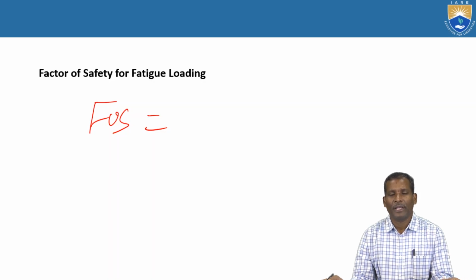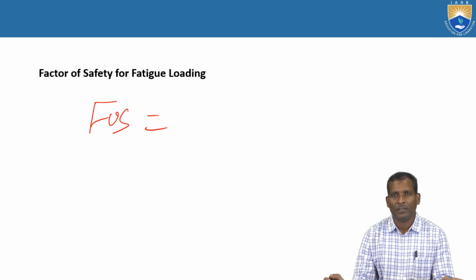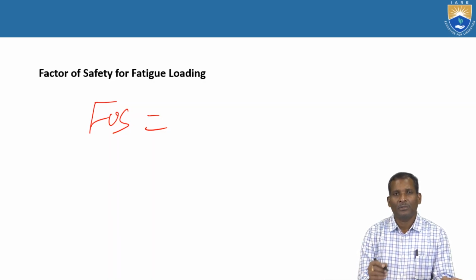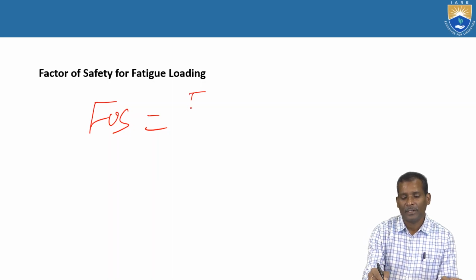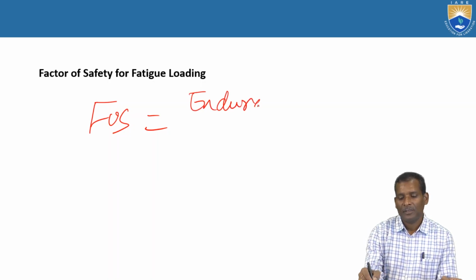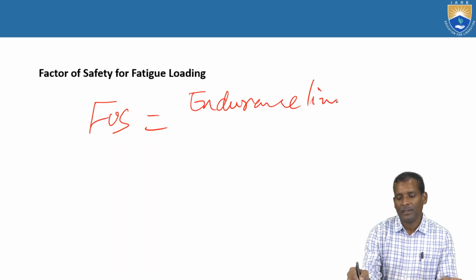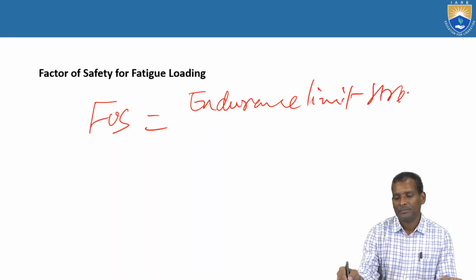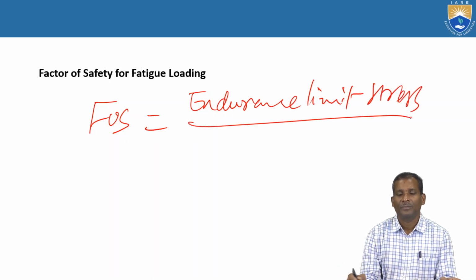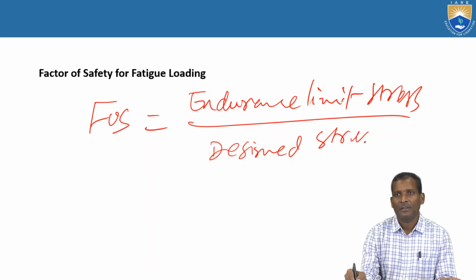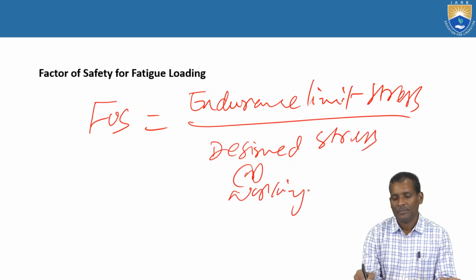So for fatigue loading, whenever the component is subjected to cyclic loads or fatigue loads, you should take the endurance limit stress upon the design stress or working stress.